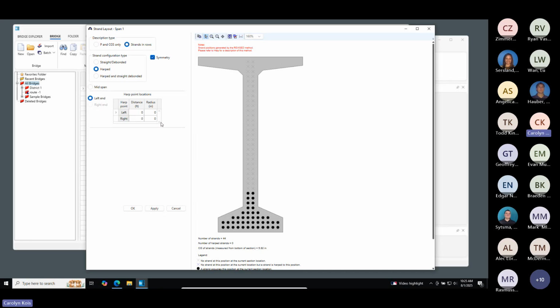So going back here, like I said, you do want to be a little bit careful when you're selecting the harp strand positions, because it won't let you cross the strands. That was basically what it was telling me just now. I wanted to show that for demonstration purposes, but I want to just re-enter this real quick here. So you'll want to start at the top because it's going to associate this row of strands with the ones you're pulling up.